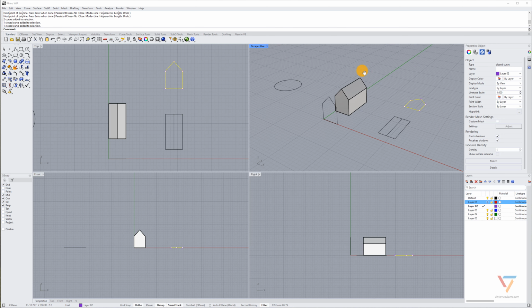To do that, let's just look here in the top plan. I know that I want to use some new commands to generate 3D objects, and I kind of want this thing to be turned 90 degrees and extruded. The command in Rhino is called extrude. There are other ways to kind of get 3D geometry, but let's start with that one.